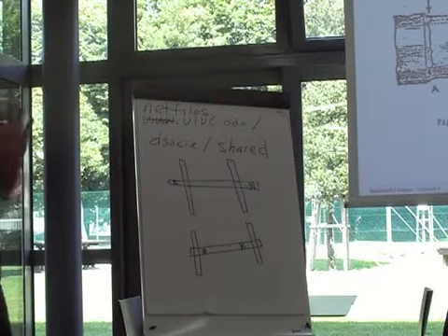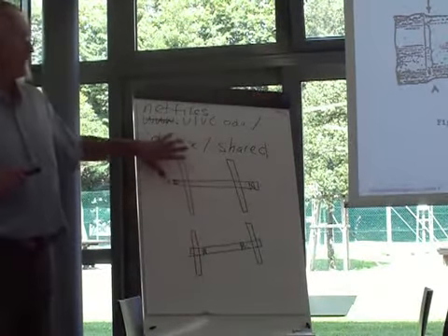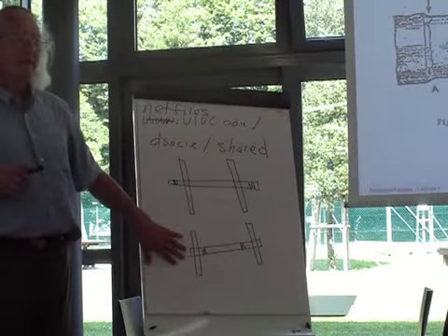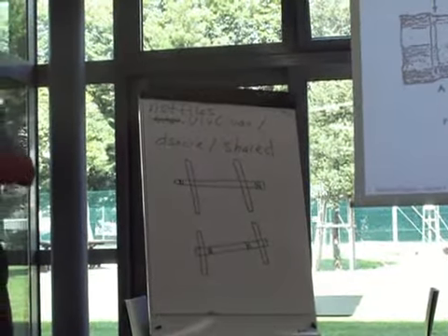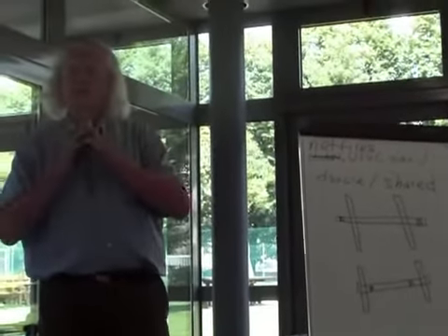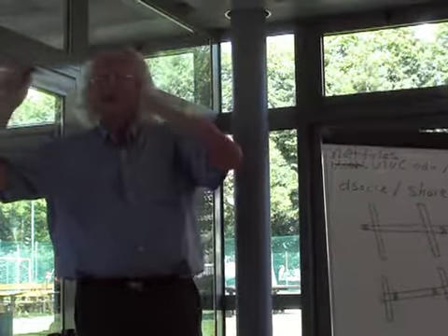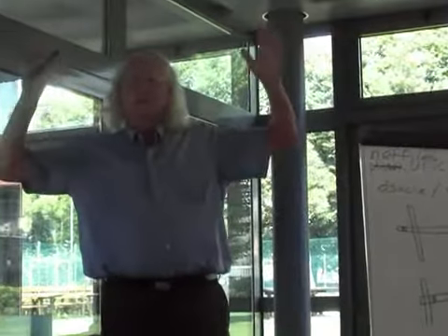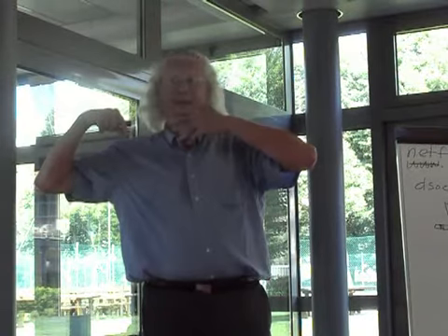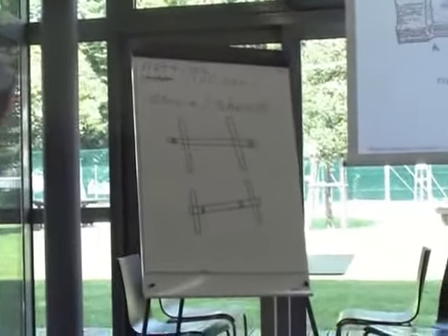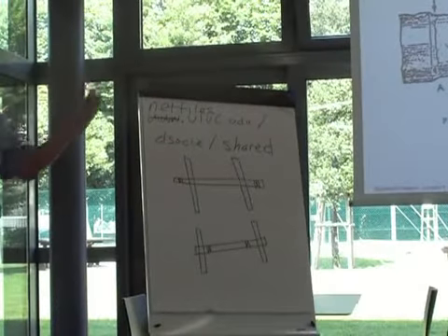What's the difference in the stresses in the axle from these 2 designs? Because remember, in 1850, this is before very much strength of materials. So there was no concept in 1850 when this was designed about calculating bending stresses and strength of materials, and no concept of stress concentration factor. Concept of stress concentration factors and stress concentrations did not come until 1910. We think these things have always been known. So what's the difference between these 2? Which one has the highest stresses?